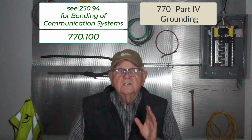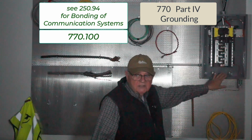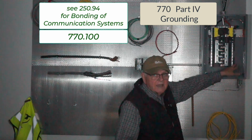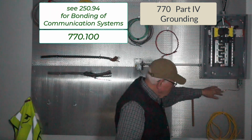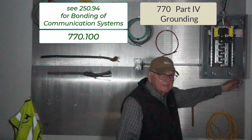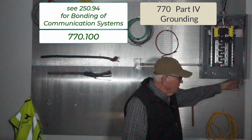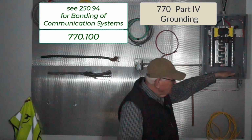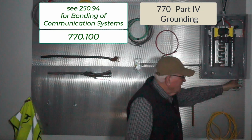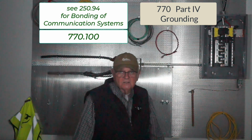termination. So the intersystem bonding termination, here's my service panel. My service panel, I've got my grounding electrode conductor that runs out of my service panel, and my grounding electrode conductor, of course, goes to the grounding electrode itself. The intersystem bonding termination device, different types, different manufacturers. This particular one is attached to the box with the lock nut, and then there's a set screw on the front of it that's tightened down, and that attaches it firmly to this grounding electrode conductor.